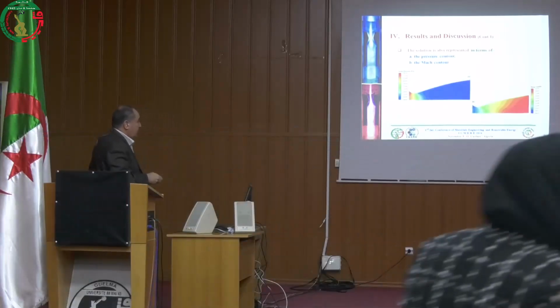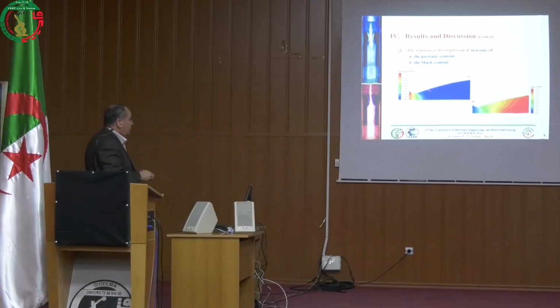We can also see the contours, here the contours of the pressure and of the Mach number. We can see the Mach number getting higher and higher. That's because the flow is expanding, the air is expanding, very high expansion. We start here at Mach equal 1 until Mach equal 3 point something, more than 3, which is something like 2,000 meters per second, I think.